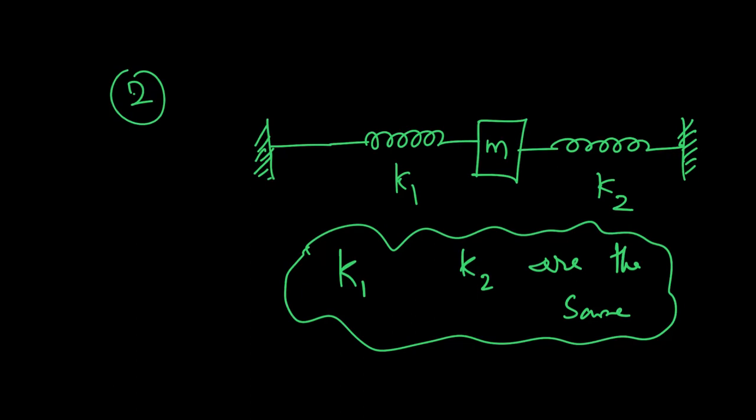So in this case, the net deflection seen by both of the springs are same, because if, let's say, I move this particular mass by 2 mm towards this side, then this will extend by 2 mm and this will get compressed by 2 mm. So the net deflection felt by the individual springs are the same, at least in the magnitude.